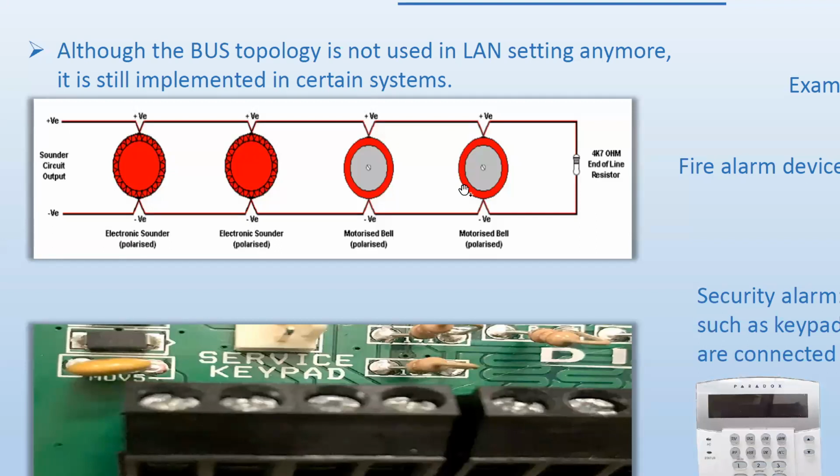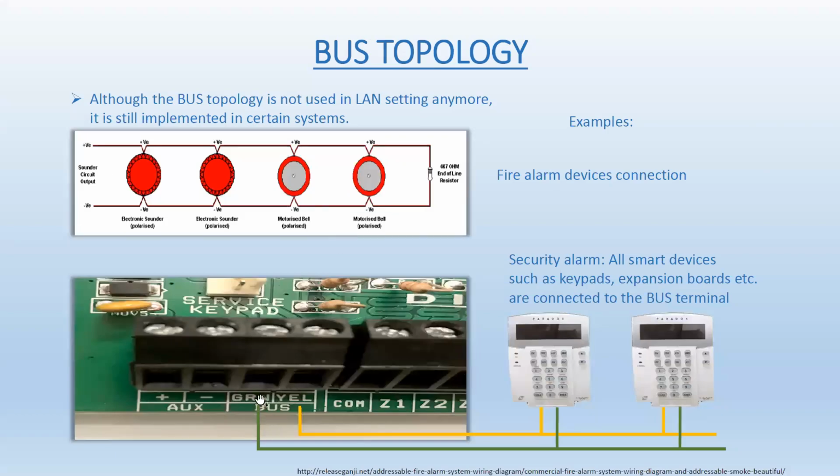All right, now, if one of the devices triggers, let's say this is a smoke detector, and there's smoke nearby, and the smoke detector is going to sense that smoke, boom, it's going to close the switch, and it's going to cause a dead short right here. So this is going to sense that, no, I am not seeing 4.7 kilo ohms, I'm seeing a dead short on the line. Oh, one of the sensors has triggered, boom, I'm going to go into the alarm state. All right, so that's one way of bus, a primitive way of having a bus.